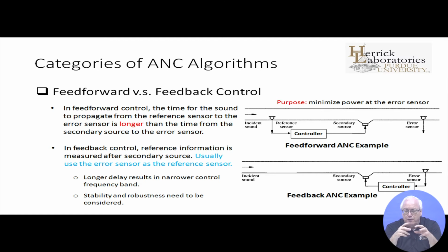And so the feed-forward sensing in that application is to put, say, accelerometers on the hub to estimate what the vibration is that's being experienced there, and then process those signals to generate the signal in the vehicle that is canceling the sound field that is being produced by that forcing down at the wheel. That's perhaps a too simple explanation of what's going on, but you have the advantage of the time delay between the forcing at the wheel and the signal transmitting into the vehicle. It gives you a chance to do something about it.